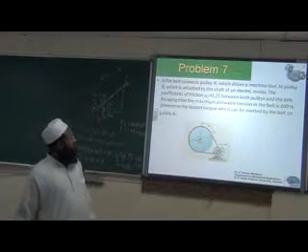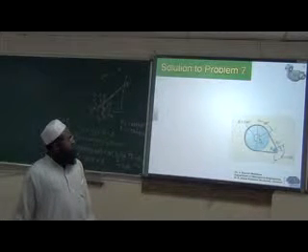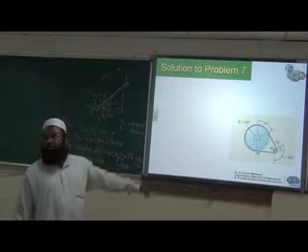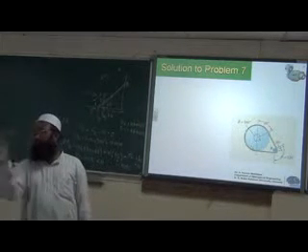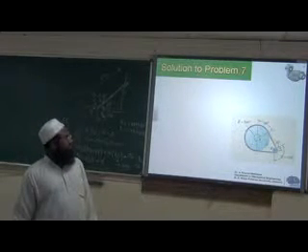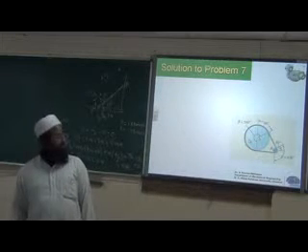So finding out the angle of lap, if you refer to this figure, this angle is 60. So the contact engagement starts here. Until here, you have the lap, both are in contact. So the total angle of contact will be 60 plus 180, 240.